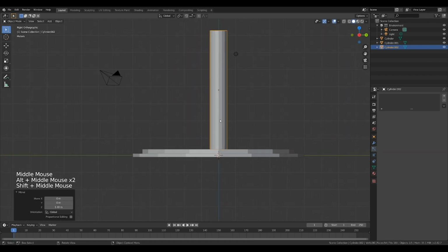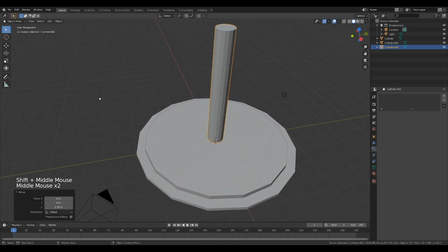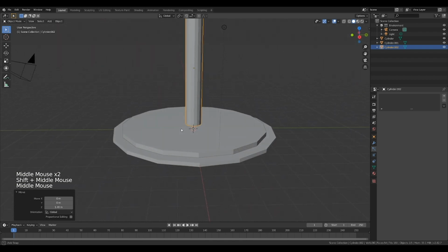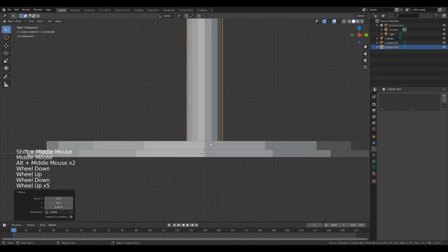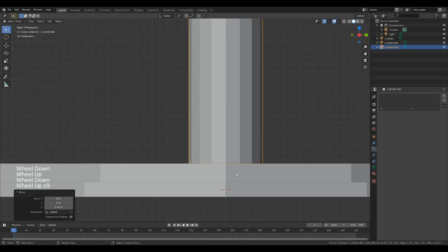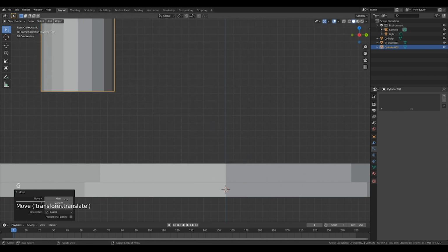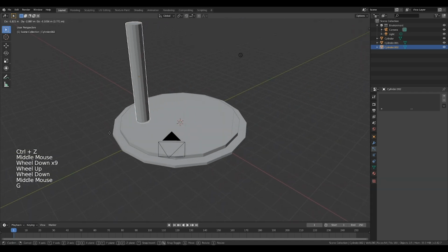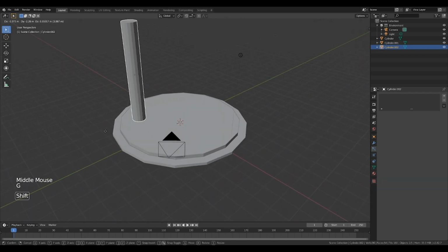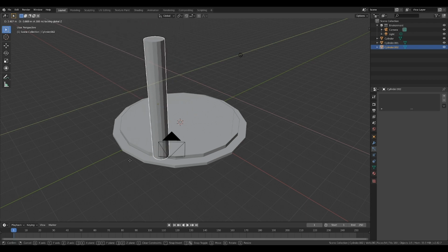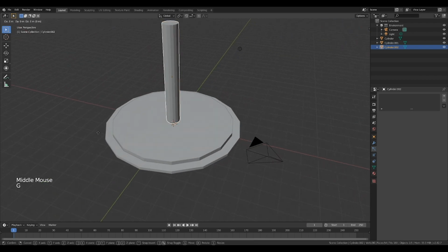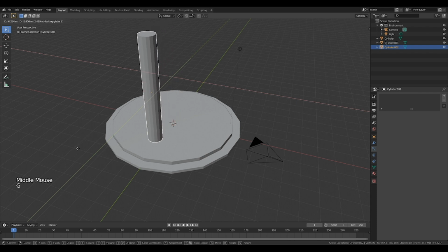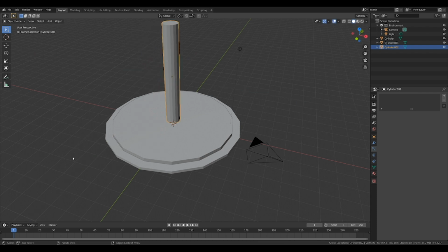That looks good. So now I need to move this only on the plane. It's already kind of attached to the top cylinder. I don't need this to float off and have all the space between it. So we're going to use the grab tool, G, and then Shift Z to keep it on the plane. So again, G, Shift Z, and I'm going to move this.